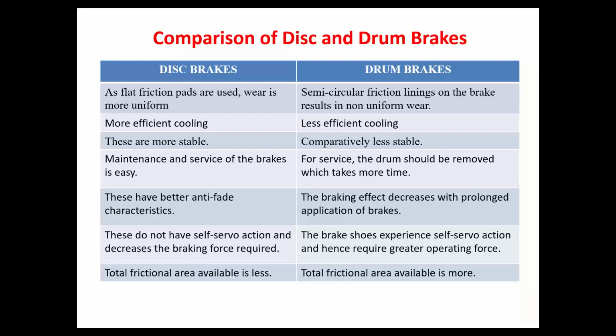That is why you can observe that in disc brakes the corrosion problems will be lesser, whereas in drum brakes, as the vehicle becomes older and older, even though the brake pad is replaced, you will not get good efficiency in braking, because the drum properties will be lost. It will corrode over a period of time. Braking efficiency will be less. So in the third point also, disc brake is better than drum brake.